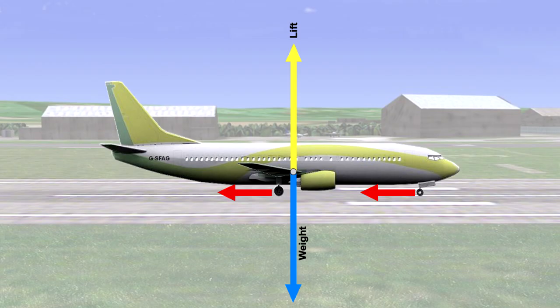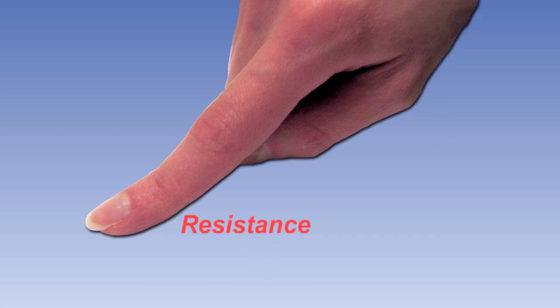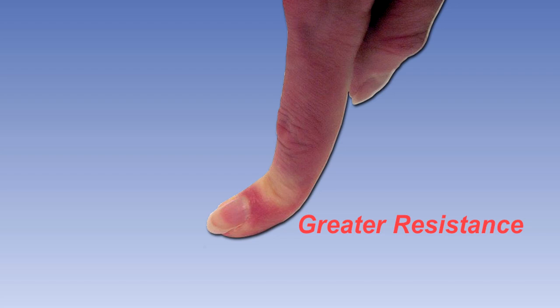Having discussed aerodynamic drag, let's now consider wheel drag. Wheel drag is basically the friction between the wheel and the runway, and is a function of their frictional coefficient and the load placed on the wheel. As an example of this, press your finger lightly on the desk and push your finger forwards. You will notice a resistance to the motion of your finger. Repeat this scenario, but now press down harder. You will notice much greater resistance to the motion of your finger. This example aptly demonstrates that the greater the load placed on the wheels, the greater the wheel drag.